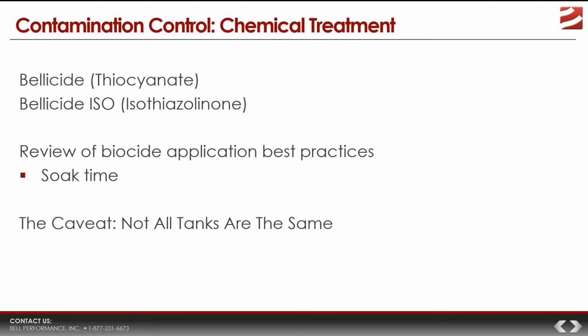And then, last thing also is, having said that, this is also where pairing the biocide with a biomass dispersant like Tank Treatment SDF becomes useful, because microbes like biomass, sometimes it shields them from the biocide. Tank Treatment SDF helps to disperse the biomass, breaks this stuff up, and it significantly reduces the possibility of needing to do a retreat two or three times, something like that. So that is why it is useful many times to consider pairing biocide with a dispersant like that.